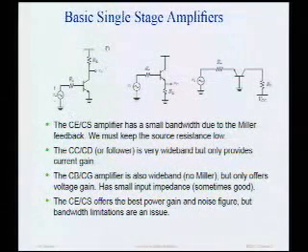If we look at single-stage amplifiers, if we're going to use a transistor, it's a 3-terminal device, right? And we're going to take one terminal in common to create a 2-port. That means we have to choose two different topologies. We can take the source node in common, or the emitter node. That's a common emitter amplifier. We can take the collector node in common. That's a common collector amplifier or a common drain amplifier. Of course, we know that more commonly as an emitter follower or source follower. Or we can take the base or the gate in common, and we have ourselves a common gate or common base amplifier. Now, all these amplifiers are good and well, but usually we don't use them.